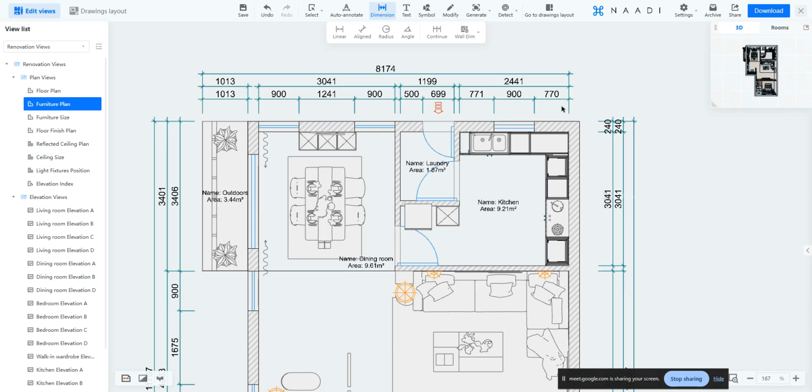So if you're seeing any discrepancies in the dimensions, or any position misalignments here, in 99% of scenarios the same misalignment is there in the model. Once you correct that model and come back here, it will automatically be updated here. Because your 2D is not a separate entity, it is an entity which is linked to your 3D model. So what you see in the 3D model is what you will observe here in the 2D. So make sure that this is always done.